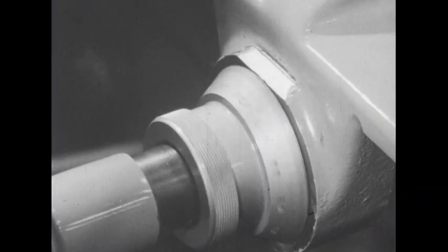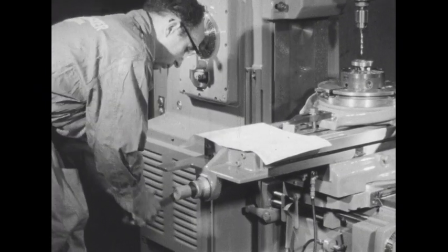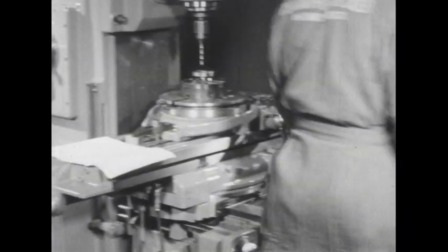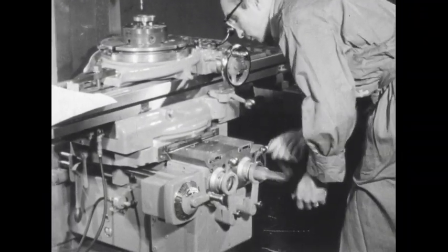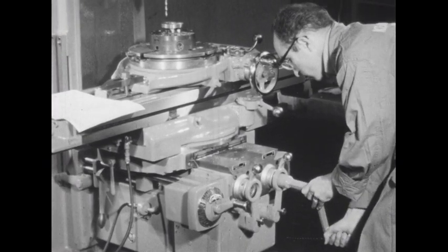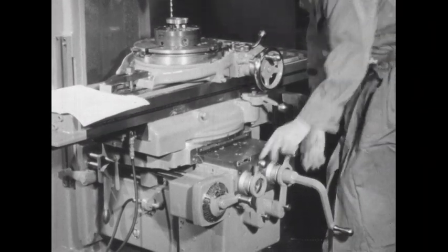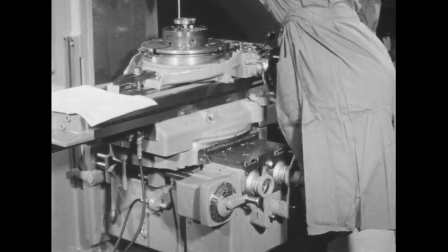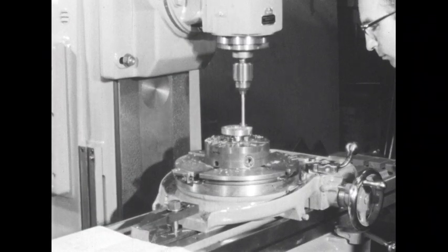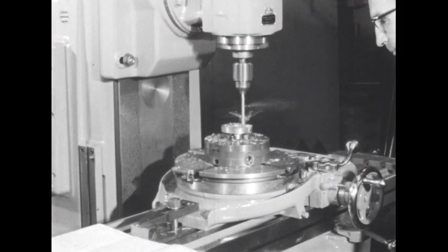This dial is attached to a lead screw. By turning the hand crank, the milling machine table with the workpiece may be located with relation to the cutting tool. The workpiece is now being located for drilling one of the holes. There are 3 dials, 3 lead screws, and 3 hand cranks on a milling machine for moving and locating the table in 3 directions. The workpiece has been located for one of the holes, and the drilling is now in progress.